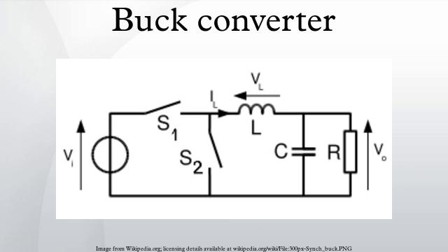It is essential to remember that, for NMOSFETs, the high side switch must be driven to a higher voltage than Vi. Therefore VG will nearly always be different for the high side and low side switches. A complete design for a buck converter includes a trade-off analysis of the various power losses. Designers balance these losses according to the expected uses of the finished design.